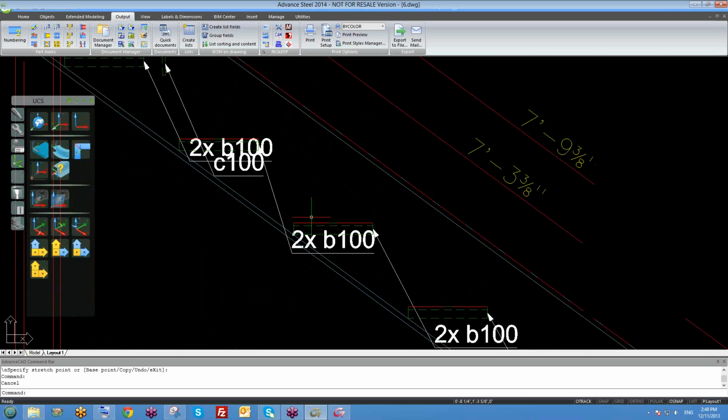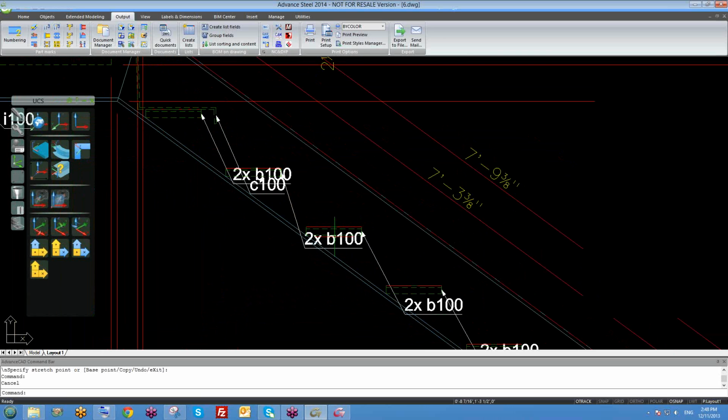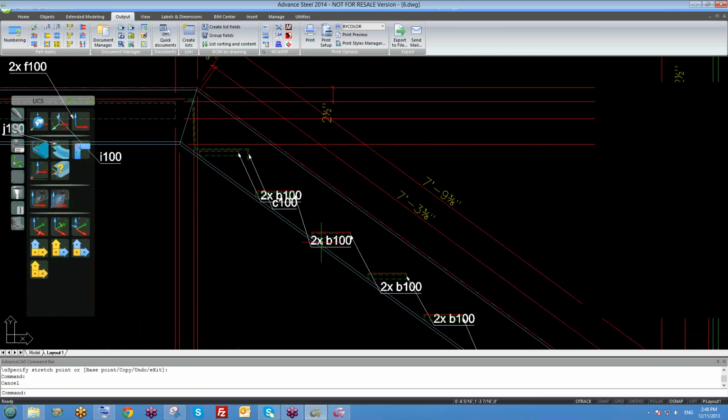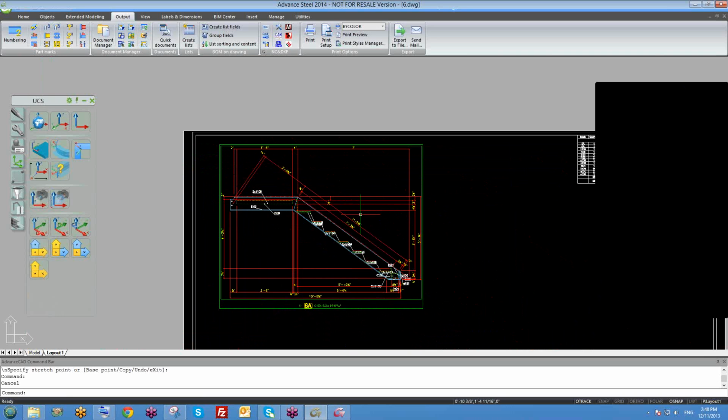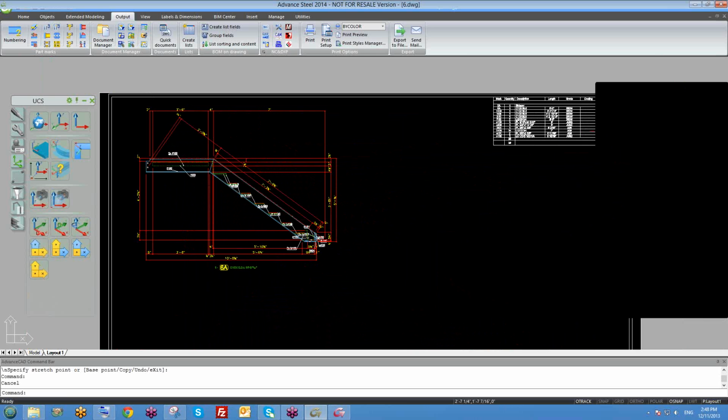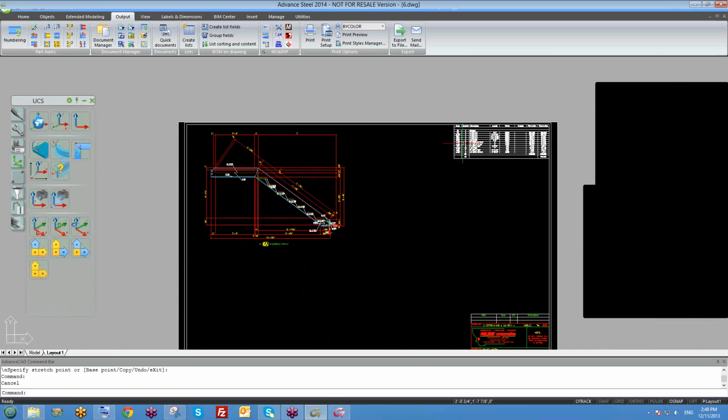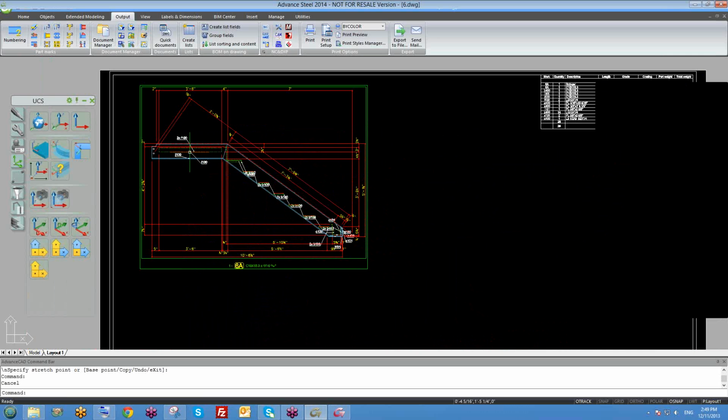If you have any trouble doing that once you end up with a project done, it depends actually on how you have your stairs, your stair pans connected to the stringers. If they are well laid in the shop or if they are bolted, it depends on that. All right. So if you have a project done and you have any trouble with your list, give me a call or send me an email. But the way it works for drawings is just place your UCS where you have your stringer and then make your drawings.